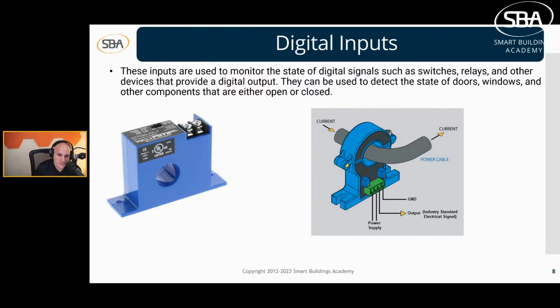You would set it higher so that it would actually show a load on the motor, because if you had it trip at a low amount, you could have a free spinning fan, like the wheel or the belt's broken and it's spinning and it draws just enough to trip the relay, but not enough to show that it's actually running under load.